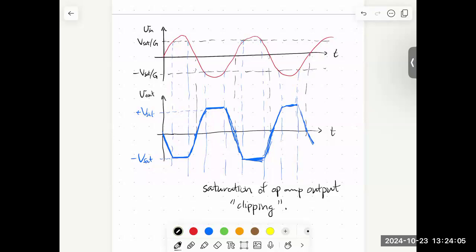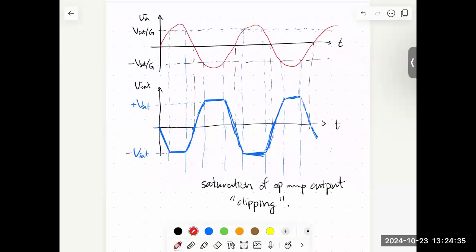Okay, so you will observe the clipping in the lab tomorrow. And so one of the things that you should do is, once you've seen that, when you're actually taking the data that you want to collect, you want to make sure that you avoid this clipping effect. That just means you have to turn down the amplitude of your inputs until it's always below the maximum allowed value.